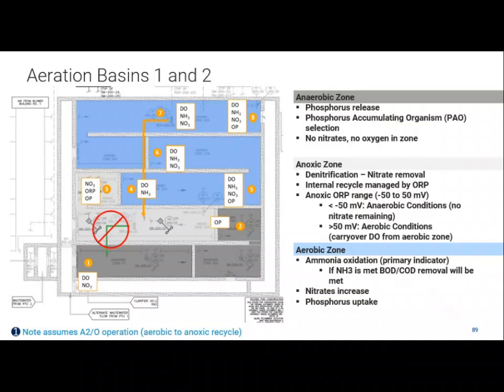All right, then you get to the aerobic conditions. DO and ammonium in a bunch of spots. Why are we measuring DO and ammonium as we go through the aerobic conditions? Exactly. Make sure you're nitrifying, right? See how much nitrate you're producing. And then they added in the orthophosphate profile. What is this orthophosphate number going to tell us?